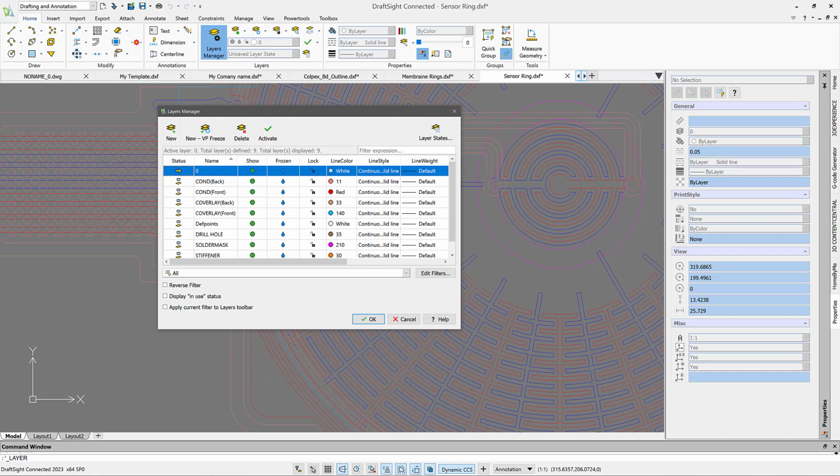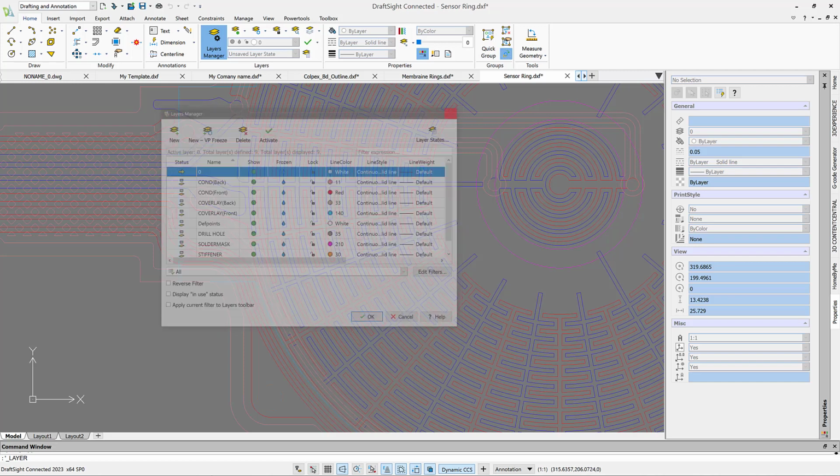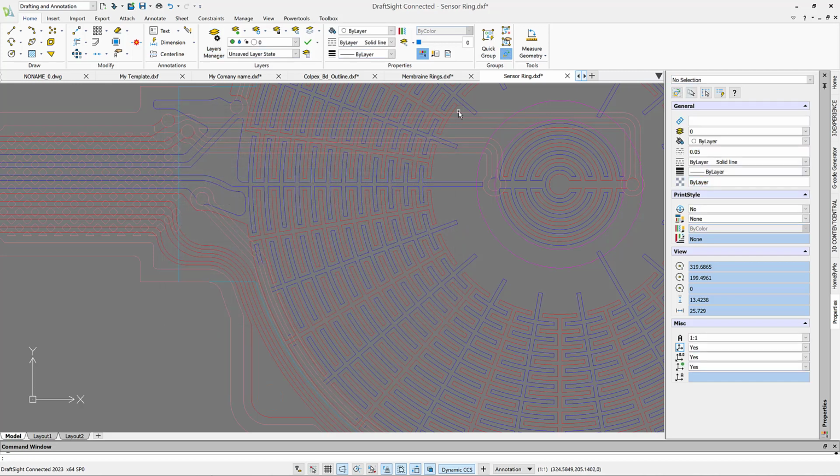Again, there are a lot of layers that you can set up depending on the software you're using, and knowing what those layers are, you can right away put specific entities on an intelligent layer, so when you bring it into the PC board layout, they end up on the appropriate layer and possibly even as solid pieces of copper that you can use to create a symbol for this complex switch inside PC board layout.